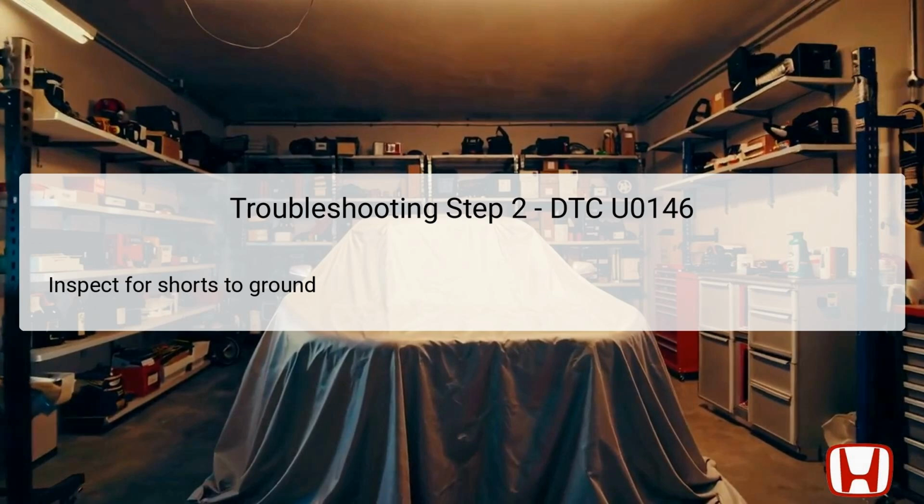This inspection typically involves a thorough visual examination, as well as electrical testing using a multimeter to detect any unusual resistance readings. If a short is found, fixing it may require replacing sections of the wire or repairing the damaged insulation. Correcting any shorts to ground is vital to ensure accurate communication between the CAN components, preventing continuous triggering of the DTC in the future. Once resolved, retest the circuits to confirm the malfunction indicator does not persist.